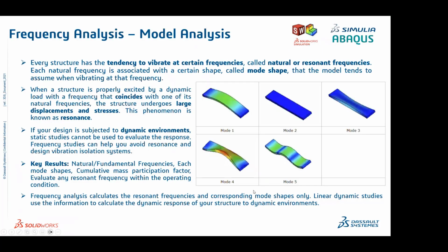So this is very important to evaluate during the dynamic event. That is why, once you perform this frequency analysis, you will understand the mode shape of each natural frequency, and you will see whether any frequency is coming within my operating design range. So if you design subject to a dynamic event, a static study cannot do it. Yes, a static study is not going to consider all these effects. In a static study, you only get the maximum displacement and strain.